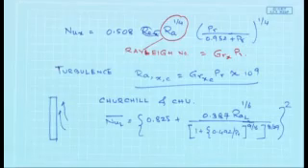So, what the researchers have done over the years is they have a huge number of experimental data under various conditions, and they start with some heuristics, some logic that Nusselt number has to be a function of Grashof number and Prandtl number, or you can express it as a function of Rayleigh number and Prandtl number.